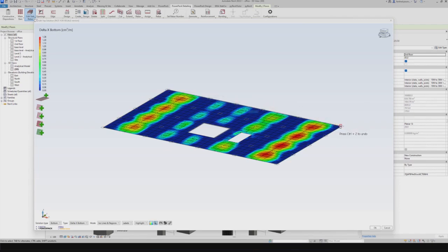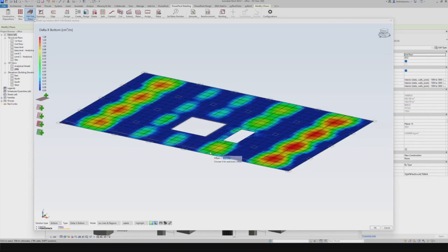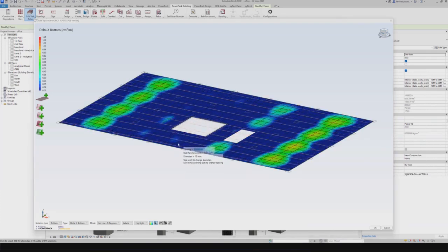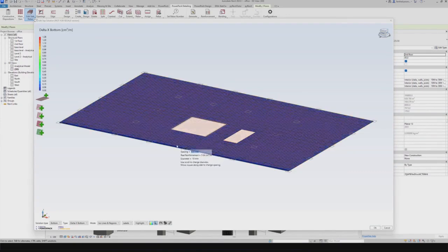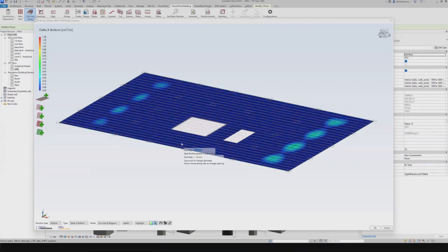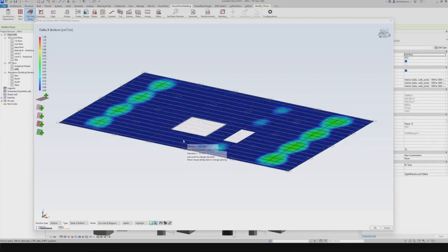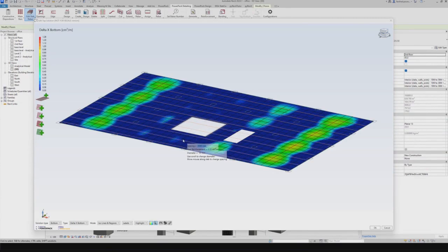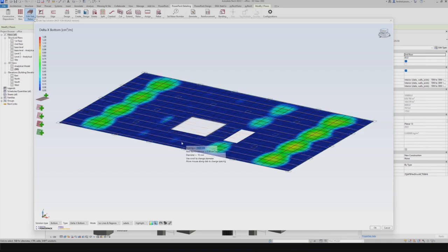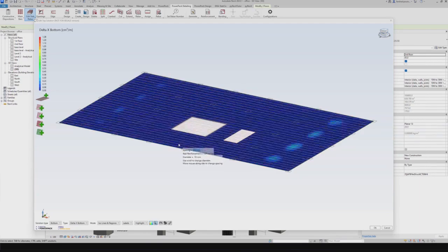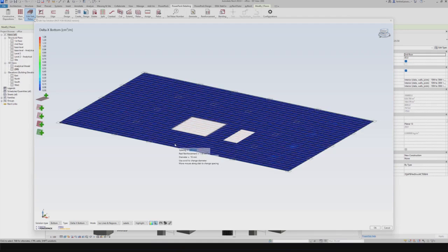There you go. You just need to click on the corners. And now I have the control to put my rebars, and this is going to be fully dynamic. For example, I can start my first rebar, let's say from 500 millimeters. And now I can start by adding or changing the spacing based on the rebar area that I require. As you see, it's fully dynamic. When I'm putting my rebars farther away, because I have less rebars, less area of steel, I'm not covering my theoretical rebars. But when I'm putting them closer, at some point, I'm covering it fully. So here, I'm going to decide that my spacing is 600 millimeters, and I will click.